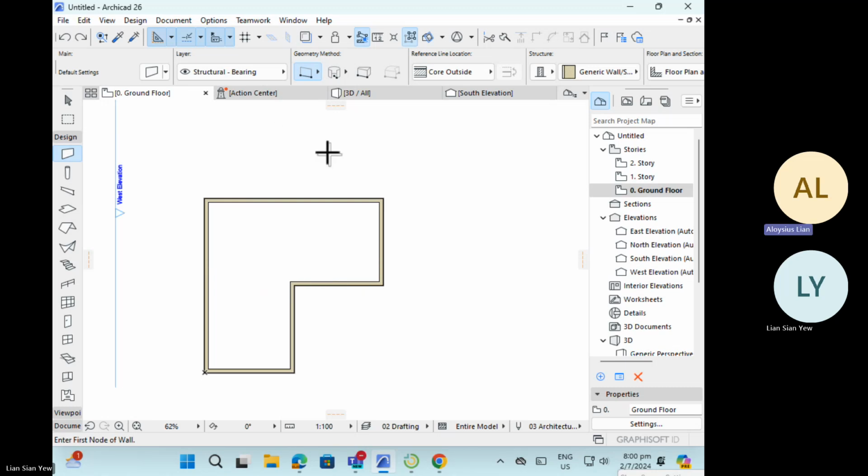So I repeat again. What you should be doing is select the wall first. Just now we did the wall as a corner to corner. So click and hold until this is the first wall selection here, right? Then you hover to this corner. Then don't touch the mouse anymore. Just type Y 4000 minus enter. Then left click once to draw the wall.